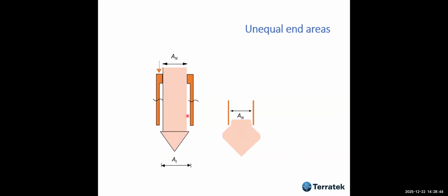And because of that, they found this by doing offshore tests, because they used to calibrate the cone or zero the readings before going into the water. And then when they put the cone into the water before entering the soil, they found out the readings were not zero anymore.